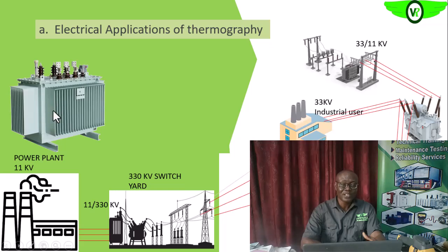So in these cooling fins, the oil will now give off the heat that it absorbed from the windings to the body of these fins of the transformer. And with this heat that is given off, the air molecules around, both the ones that are trapped between the fins and outside, will absorb the heat from the body of the transformer and take it out. So which means that as the transformer is working, these cooling fins expectedly will show some heat, that is because that is their work. Are we getting it? So that heat, we can look at it with the infrared camera.